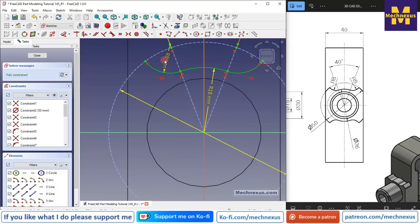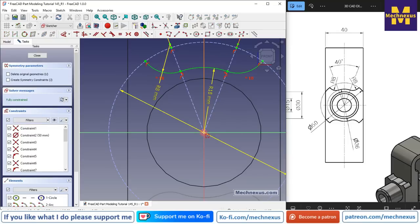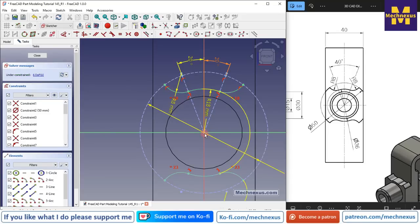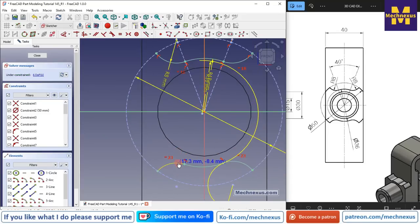And now here you might think why we cannot use the mirror. So if I select this and use the mirror tool, it will get mirrored. But the problem with this mirror is that it does not make relations like the coincident and tangent relations given here. If I mirror it, okay, but if I try to move it, you can see that the center is not coincident.